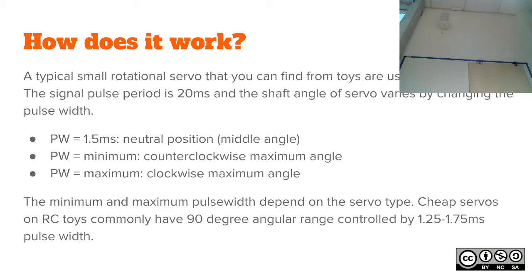And guess what we have here? This is the state of the art cheap servo. Okay. Yeah, so very simple device. You just have those 3 wires and pulse width. Pulse width is telling the angle, for example, from minus 90 degrees to plus 90 degrees.